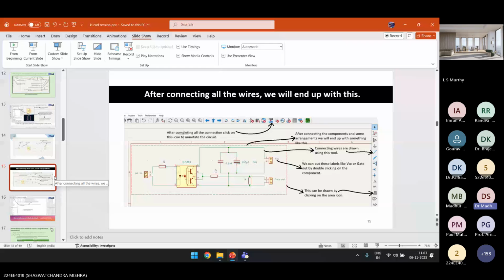You are driving the battery with the buck converter, which is generating from the solar module. The buck converter driver generates the gate pulses, and you are giving those gate pulses, which is a PWM, to the power circuit switch. There is only a resistive load required, with 10 to 15 volt amplitude, not more than that. That is your PWM voltage range. Am I right?